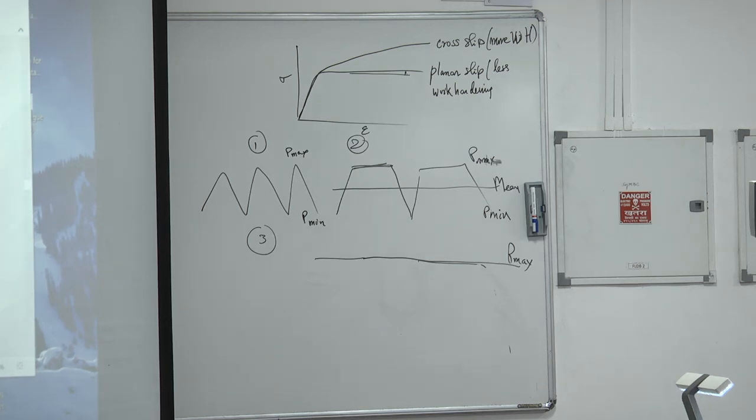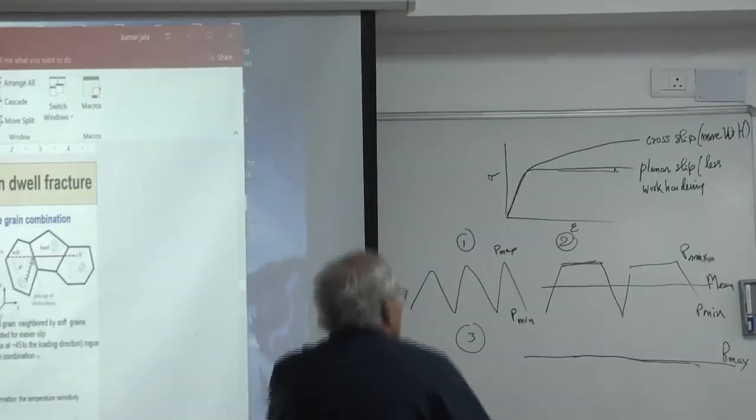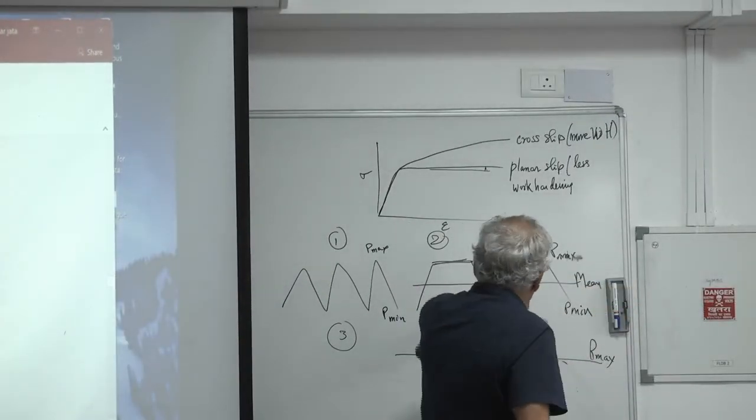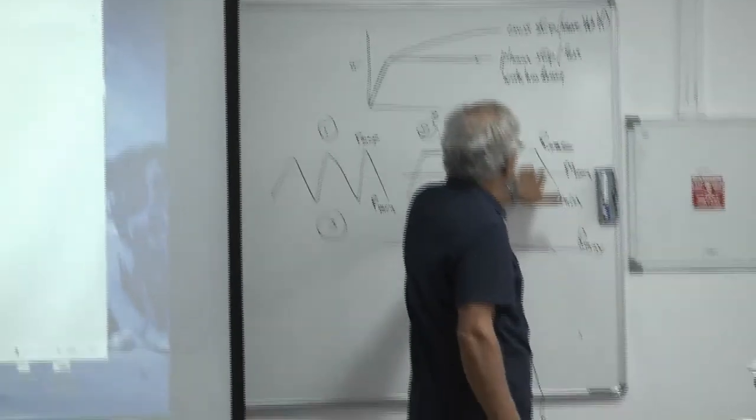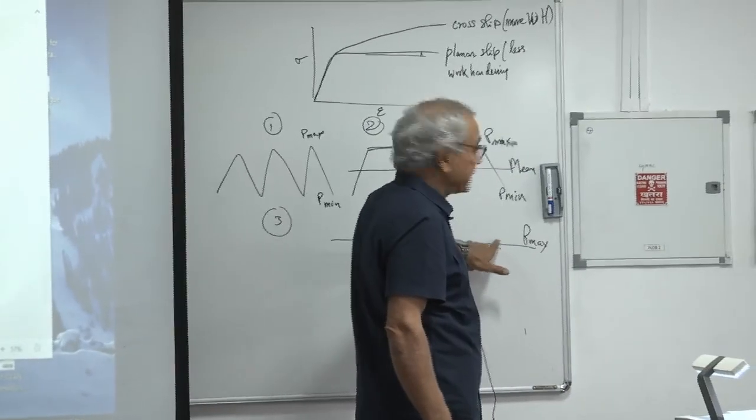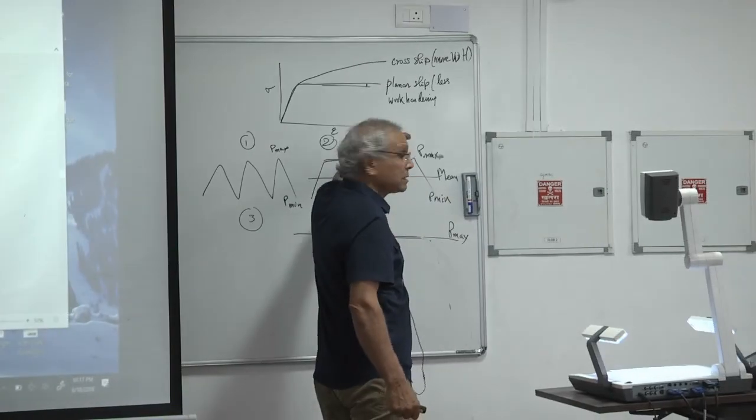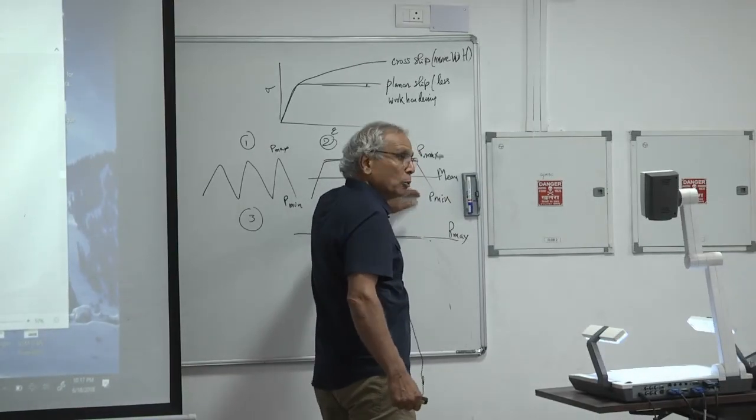This is the mean stress, and how it varies affects the fatigue strength. You can see right there, that is your mean stress, right? If you bring the mean stress down here, it will be different from taking the mean stress up here. You can take it to more positive loads, or to more negative loads.